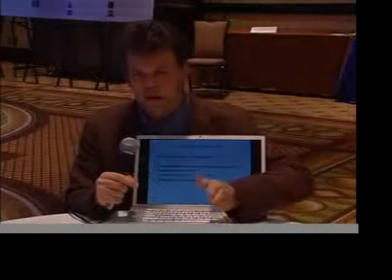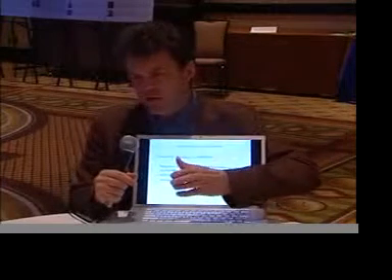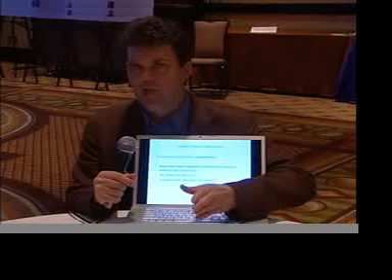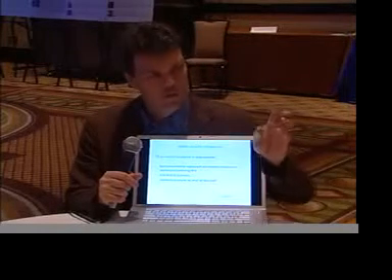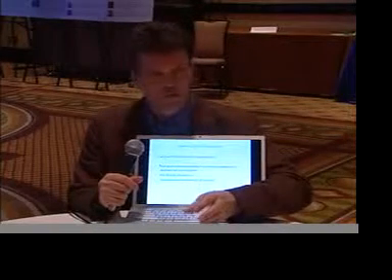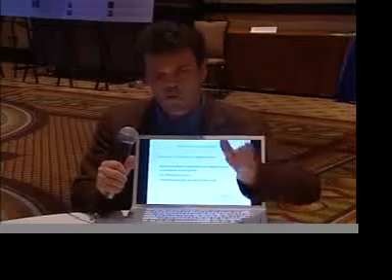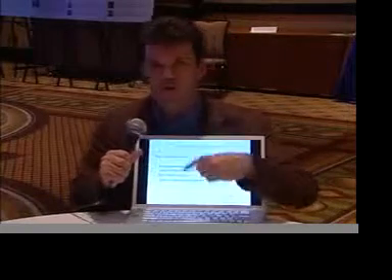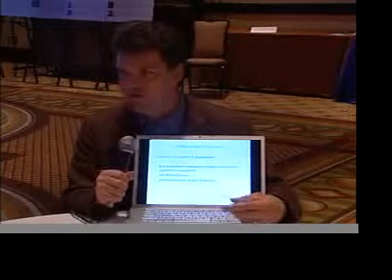And beyond that, if taking it to the other extreme, if we've got blackwater treatment in the basement of a building and we're wanting to reuse that for cooling tower use, well, then we'll have screening, biological treatment, ultrafiltration through membranes, maybe some UV disinfection, perhaps reverse osmosis, chlorine disinfection, because you've got multiple barriers of disinfection, which gives you a higher quality pathogen reduction capability, and therefore you know that it's safe. Well, that comes at a cost.